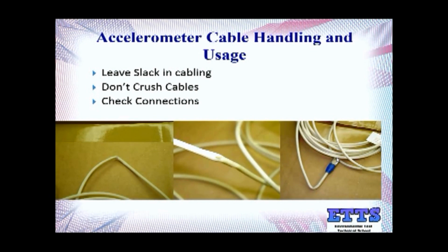Here is a kinked accelerometer cable due to the fact that the technician used too short of a radius in their cable routing. Here you have a cable that was crushed. Don't crush cables. Be aware of where your cable is routed at all times. Don't sit a fixture on top of it. Don't torque down a fixture on top of it especially. But be aware, don't step on your cables either. Be aware of where your cables are at all times. And here again is another kinked cable due to the fact that proper radius was not used when routing the accelerometer cable.